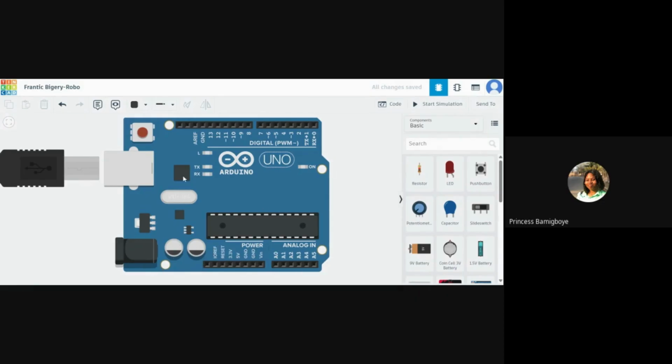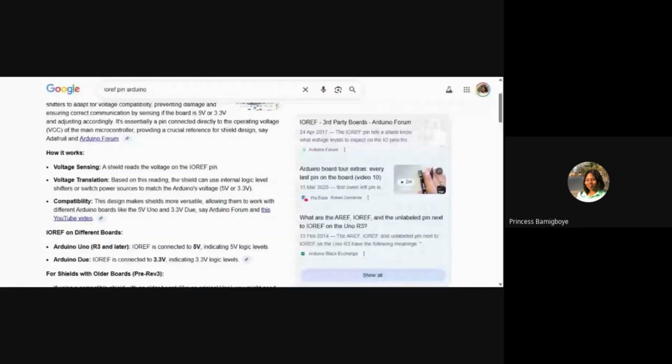As it's working with 5 volts, this shield, don't go and be using 12 volts. Don't go and be demanding 12 volts, because the Arduino does not have it. Don't go and be demanding 7 volts, because the Arduino does not have it. It is providing and working with purely 5 volts. So that 5 volts, or the 3.3 volts, whatever, work with it. So let me show you.